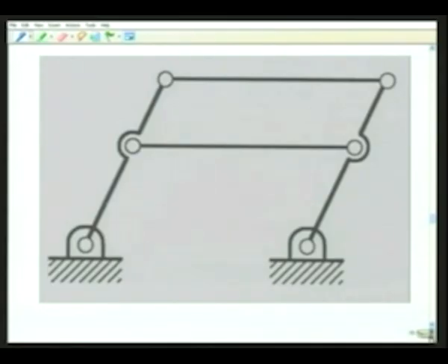So in this parallelogram linkage, if we add an extra coupler which is parallel to the original coupler, then what happens? As we see, now n has become 5, and due to this extra coupler, we have introduced two revolute pairs at its two ends, one there and one there. So J has become 6. Consequently, from the formula we get F equal to 3 times (5 minus 1), that is 4, minus 2 times J, that is 2 times 6, which is 0.